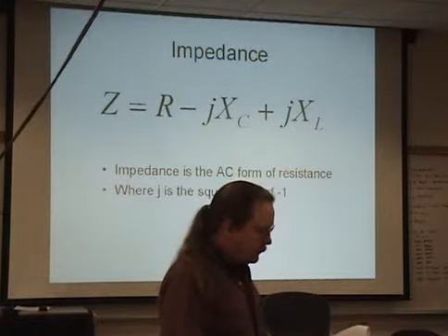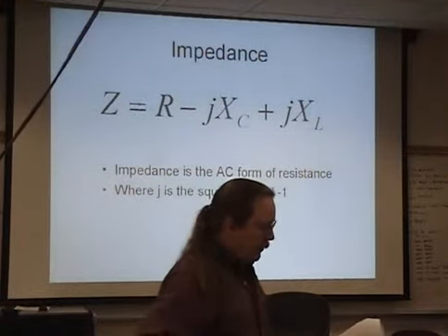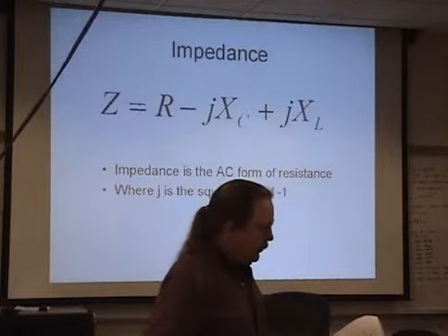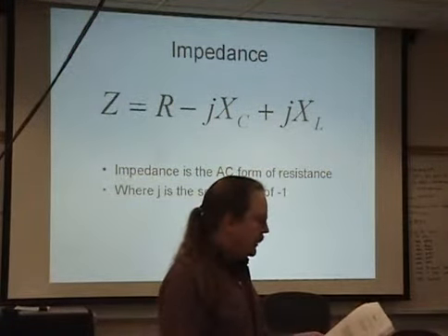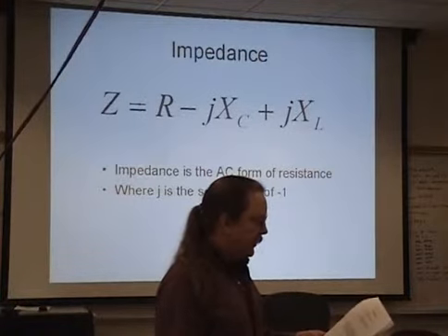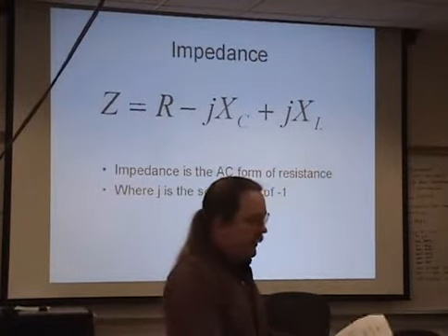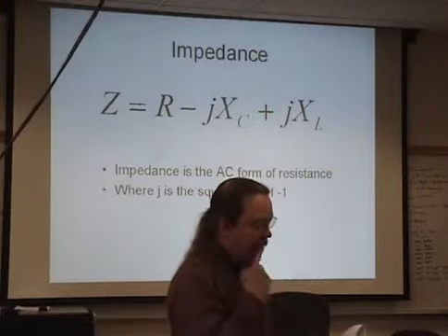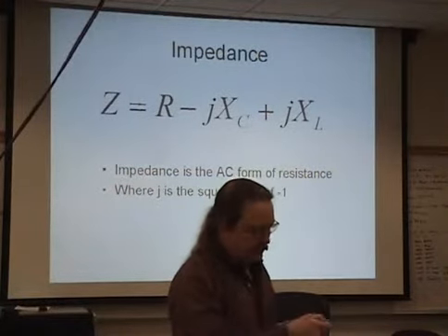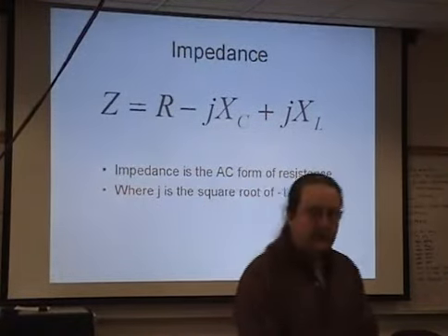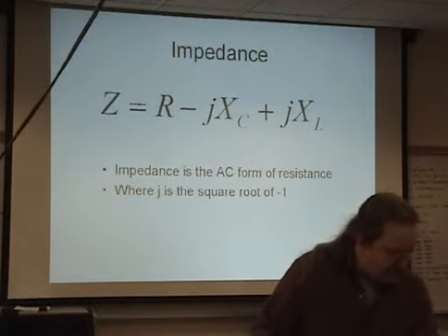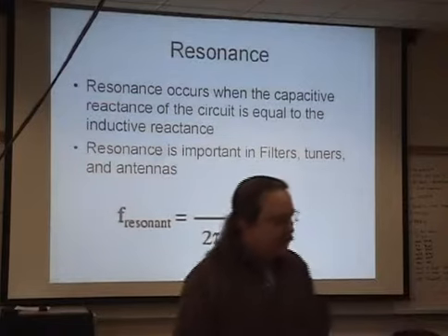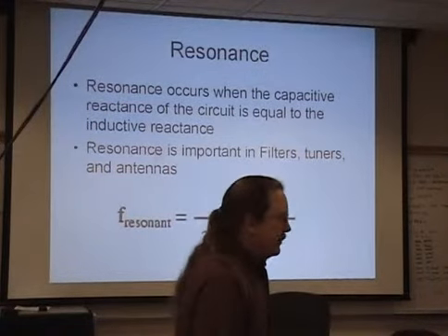In a superhet, you always have your 4 different frequencies. You have the local oscillator, you have your input frequency, and then you have the local oscillator plus the input frequency and the input frequency minus the local oscillator frequency. So you have 4 frequencies coming out the mixer stage of the superhet. At that point, you need to filter it. So you use resonance to make sure that you're picking just the right frequency.